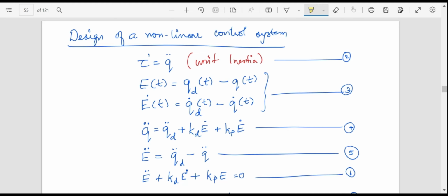The reason is that this controller uses computed torque control to modify the system and effectively decouple and linearize it. First, let's calculate the servo based portion. To calculate it, we equate the system assuming unit inertia.